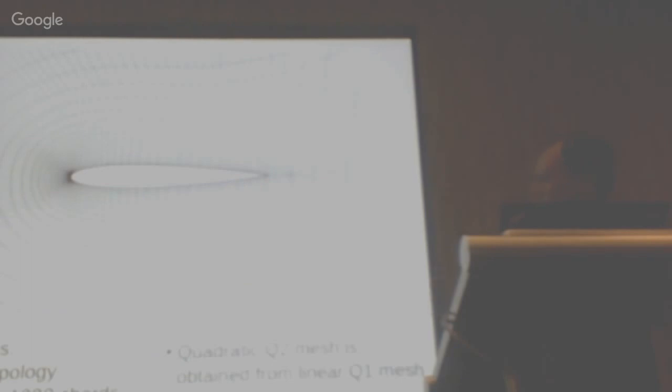We also modified the NACA equation to perform a collapsed trailing edge for the geometry. It looks like this. This is a plot of a linear mesh. If you zoom in enough, you'll see that the leading edge is composed of straight edges. And this, again, is an iteration about 5 minutes to reach machine zero here. This shows different meshes, either linear or a quadratic one, with a second and third order scheme.